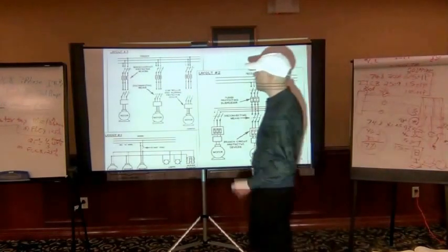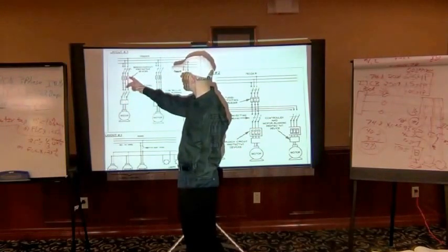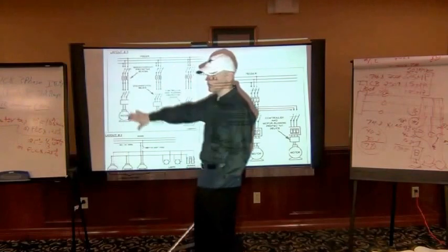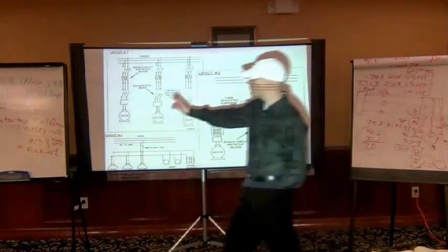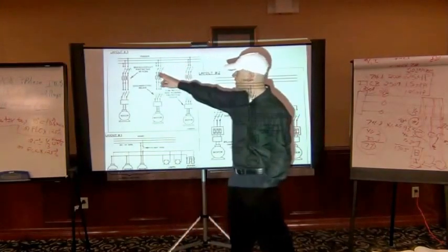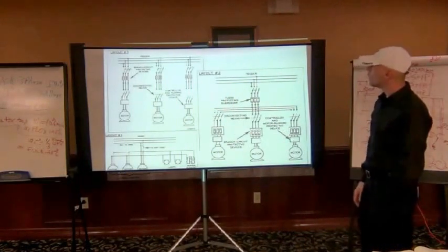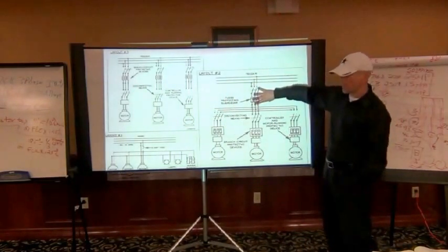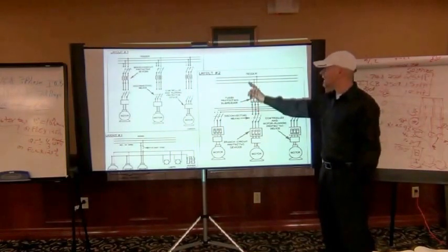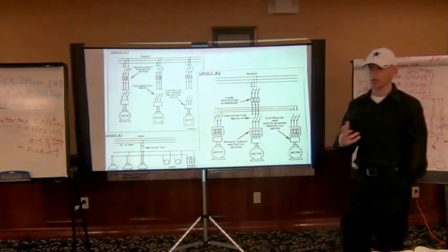So you can lay out a motor, especially a group motor, you can have a set of feeders with a main over here. Then you can have a separate branch circuit protection device, then also a separate disconnect and heaters, all by itself like that. Or you can even just have this part itself, individually. Or you can have it as a set of feeders with multiple motors, each one having its own protective device. Or you could have a set of feeders with one main subset of feeders where you've got a protective device, and then another protective device on individual motors as well. So there's a couple ways you can lay out group motors.